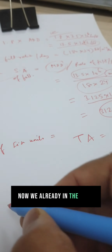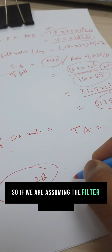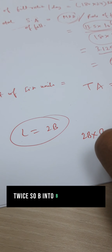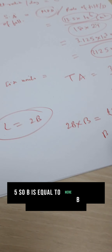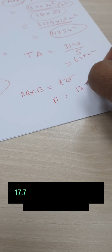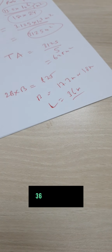Now the given in the question is that length is twice of breadth. So if we are assuming the filter bed as rectangular in shape, it would be 2b into b is equal to 625. So b is equal to 17.7 meters, or you can say 18 meters. So L will be 36 meters here.